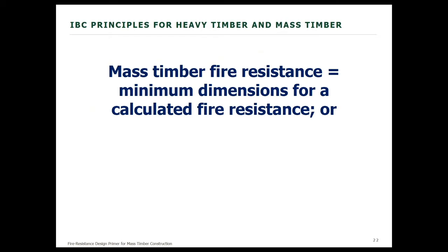It's important to note that you could also have both a calculated fire resistance of the exposed wood combined with added fire resistance of non-combustible protection on the surface of the wood. It's a very significant and important point. This is what will distinguish wood from steel in regard to fire resistance methods. For wood, you can determine the fire resistance calculated according to the calculation method for exposed timber for the member. Then you can add the fire resistance afforded by the added non-combustible protection to come up with the total fire resistance of the element.